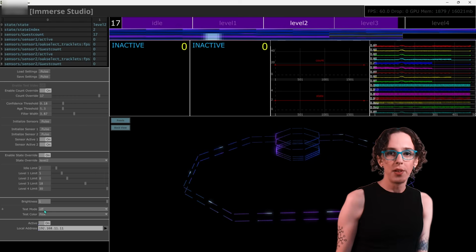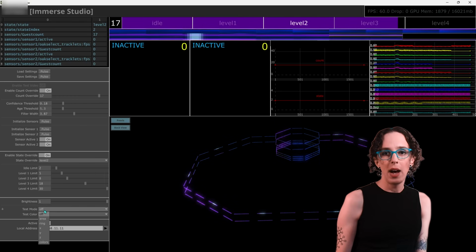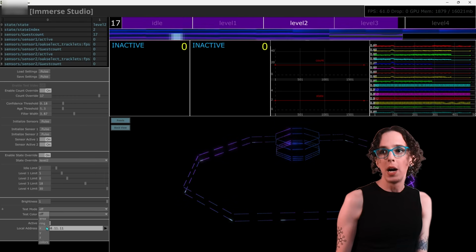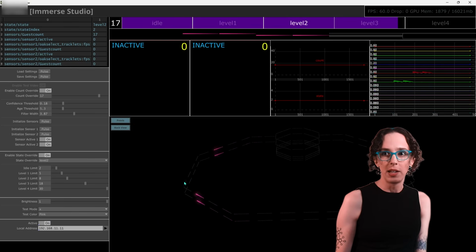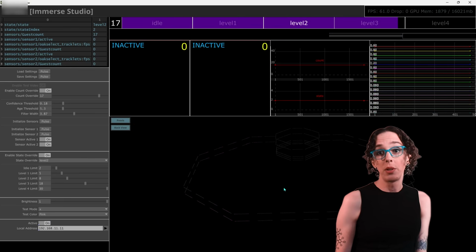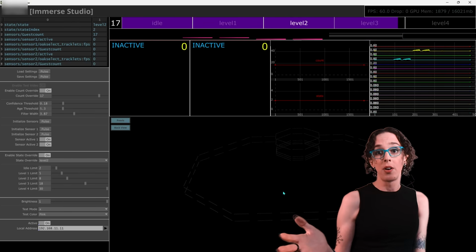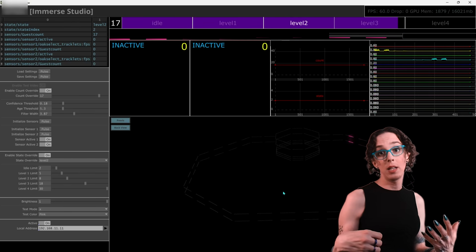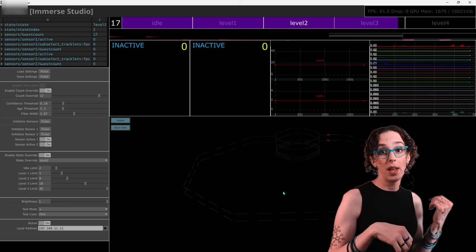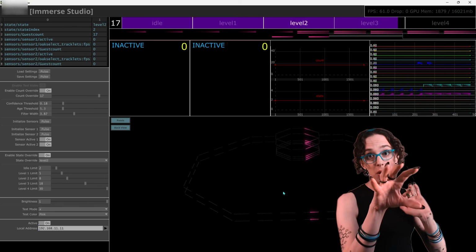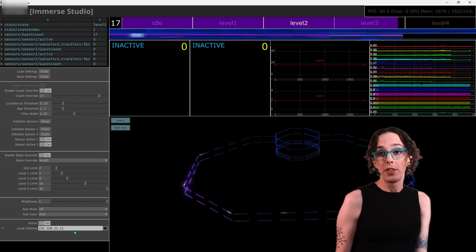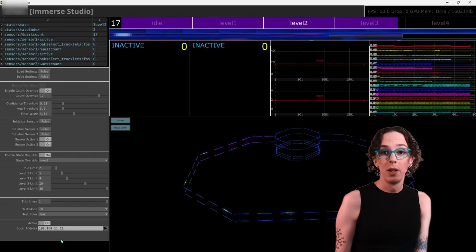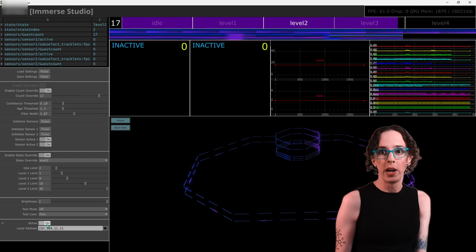I also added some testing modes, so I'll get into how exactly those work. There are different modes that would do a sweep along different axes. This is really useful when we were trying to make sure that everything was mapped correctly, so that we had the right DMX setup for each individual light bar that was out there. And then finally, we have a control for DMX output and a toggle to switch that on and off.